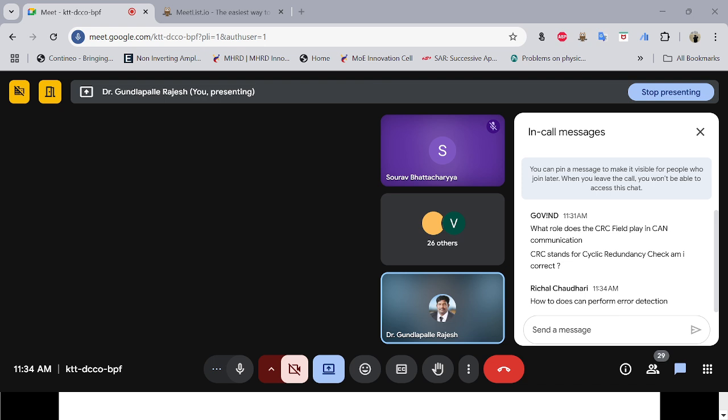So if you add everything, the bit stuffing will be done right from the start of the frame to the CRC sequence, and the acknowledgement field is reserved from the first delimiter to the end of the frame.